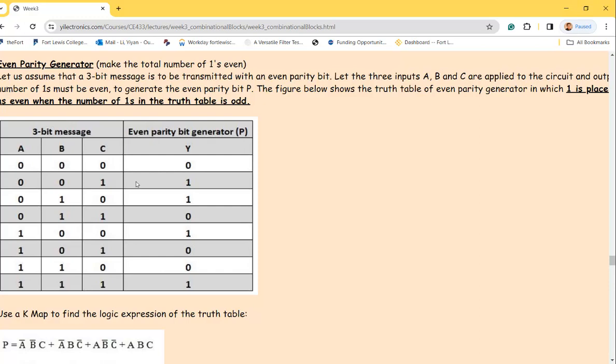Yeah, because the receiver and transmitter both know that you are using an even parity system over here, right? So you are sending an even number of ones, and that's the agreement between the receiver and the transmitter. So it just checks if the number of ones received is even? Yeah, at the receiver side. Oh, okay. So if you have 2 bits getting flipped at the same time, then you won't be able to check it, right? So it's not perfect, but it's still being used in a lot of places. Okay.